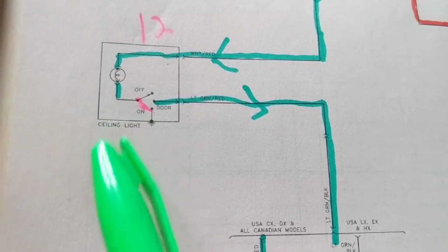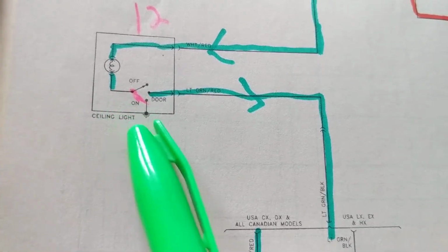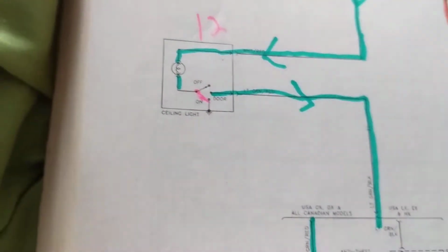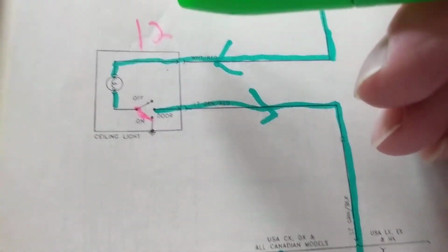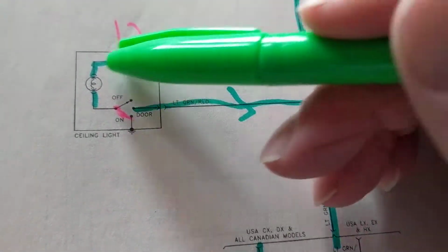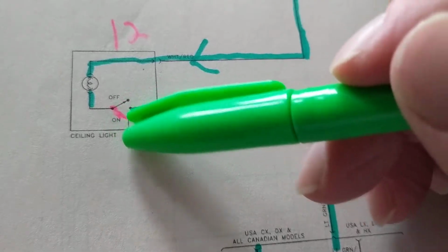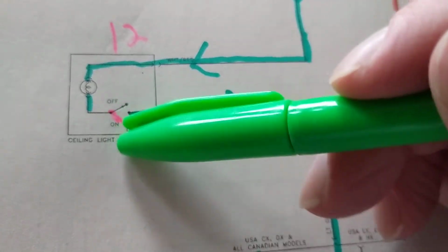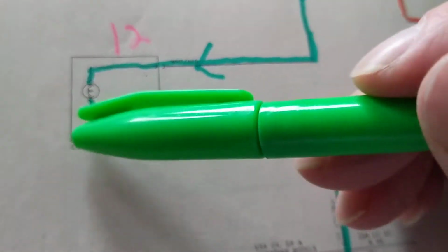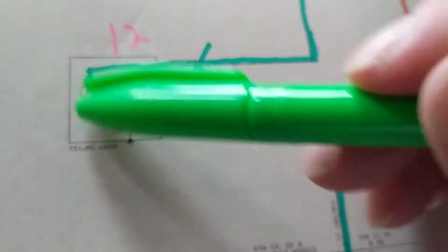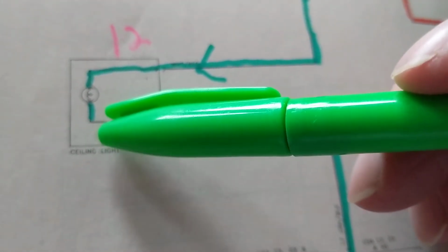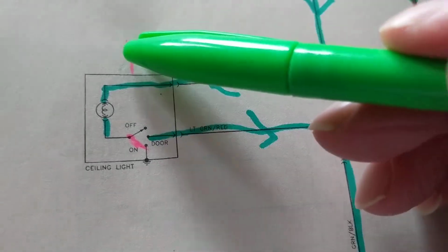But let's say the switch is broken. Right? It's not making contact to ground. How much would I measure over here? Guess what? 12 volts. Why 12 volts? You're going to say, Joseph, didn't you measure 12 volts over here? So now you measure 12 volts over here also? Because there's no current flowing. How do you have a path for it to flow? If this is open, it's not going to ground. There's no voltage drop. If I have 12 volts here, 12 volts here, I'm connected to the battery, but this side is not connected to ground, pulling it down to 0 volts. So 12 volts here, 12 volts